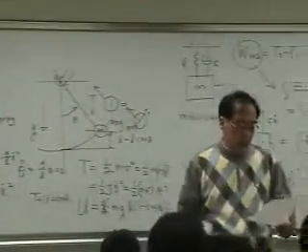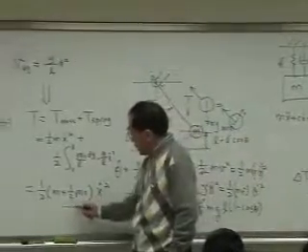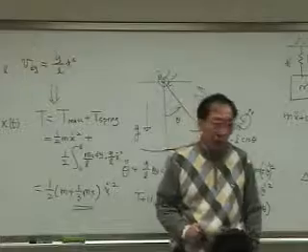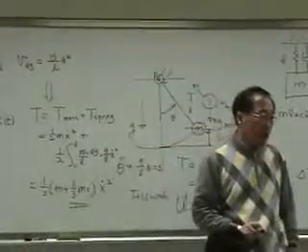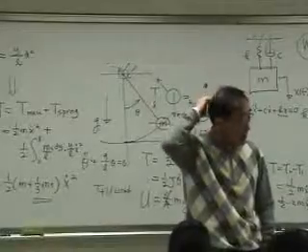Yeah, that is correct. So if we consider the mass of a spring, then only 1/3 of the mass of a spring contributes to the total mass of the vibratory system.